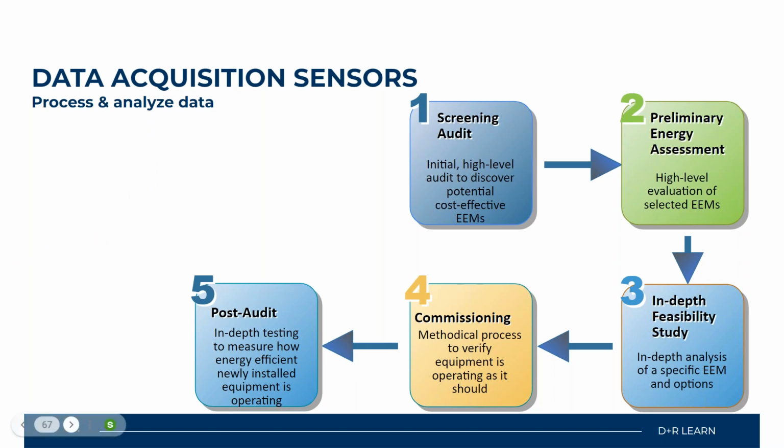Now, the audit will start with potentially looking at any type of logs that you have and evaluating your power consumption at that point, right? And even watching your system in operation as it stands. Once that is completed, there are questions that need to be answered. You know, what type of issues exist? Do we need to perform an upgrade? Once again, do any urgent repairs need to be made, or is all our maintenance up to date? These are the questions that are going to come up during your screening audit.